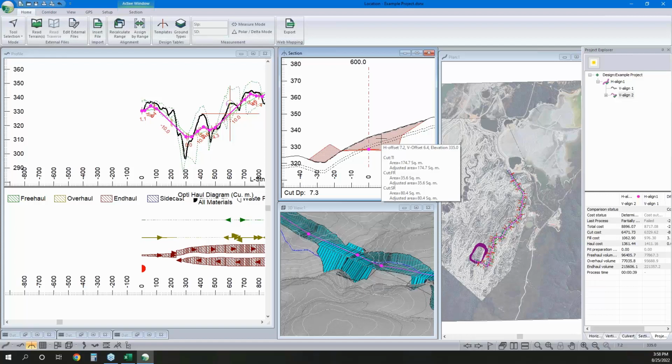Excellent. Thank you, Matt. And we have another comment here, maybe needs clarification. So less cut being tabulated, but also more fill is being used because the subgrade surface is lower. Yep. So I think I know what he was getting at there. Yeah, he was referring to when we were adding the stripping in.